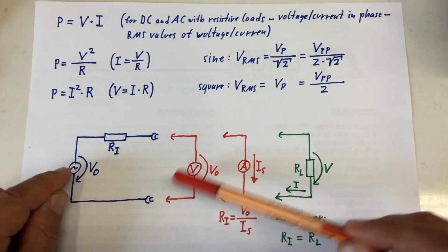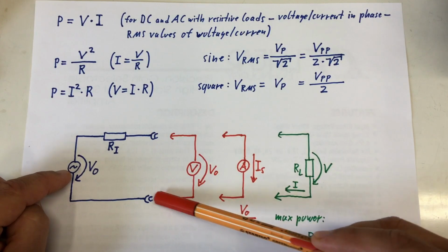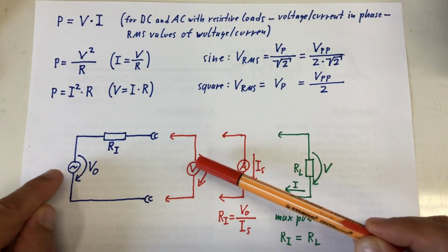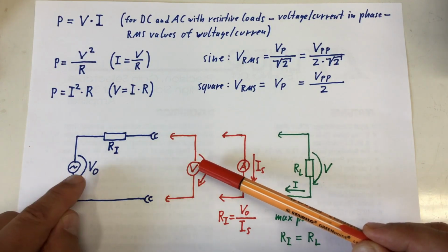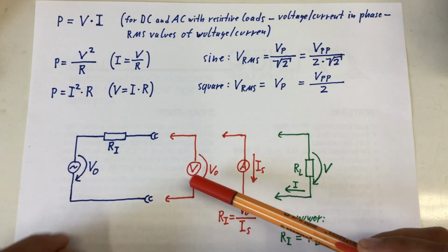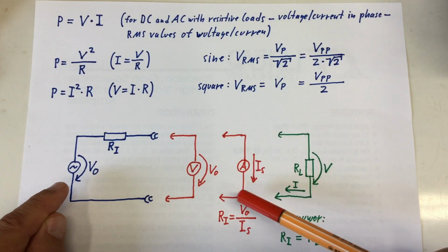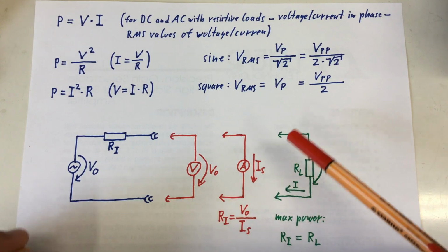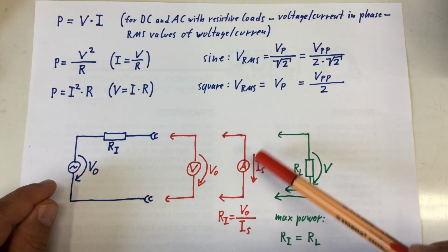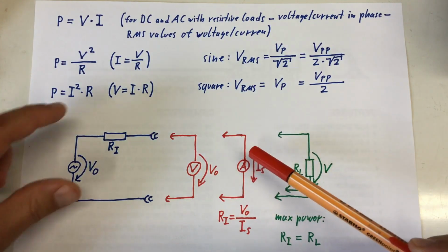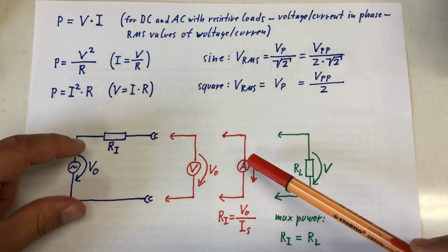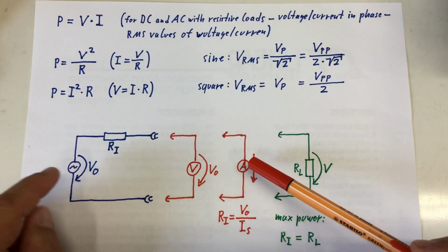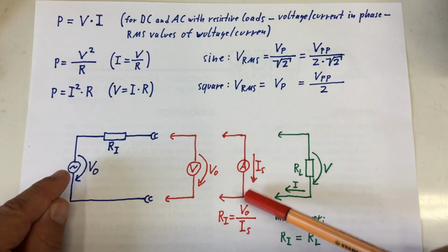Now what can we measure? We can measure the output voltage without any load, so no voltage drop here. So we are actually measuring the V0 voltage without load. Or we can short circuit the whole thing with an ampere meter and we get the short circuit current that thing can deliver. Word of advice, not all voltage sources survive a short circuit.